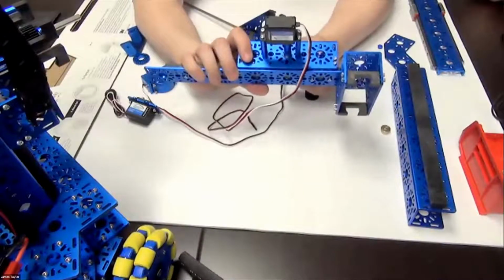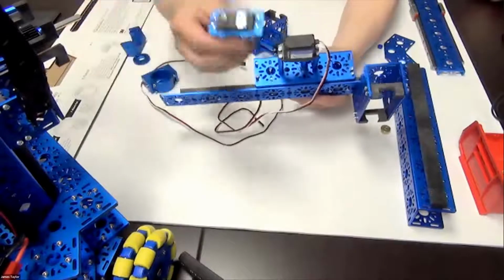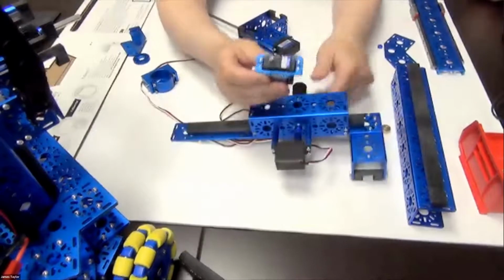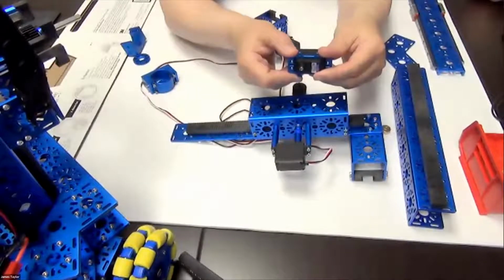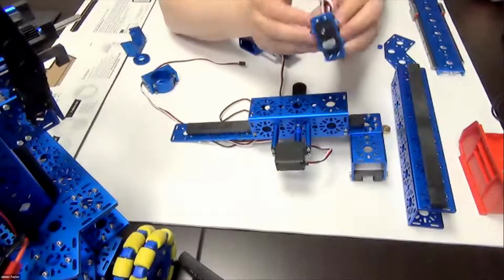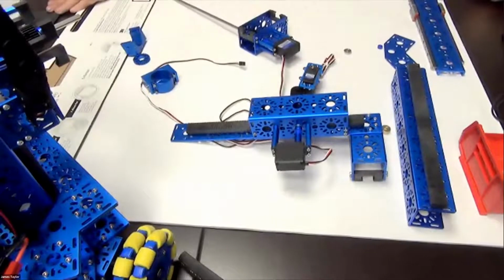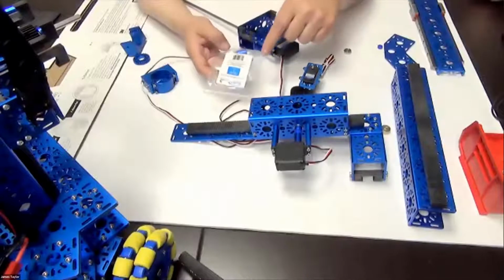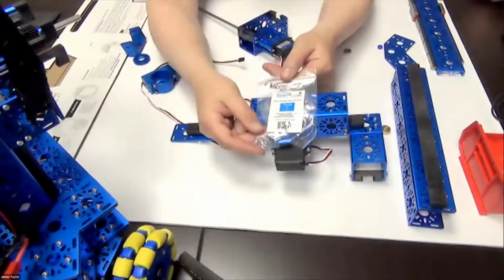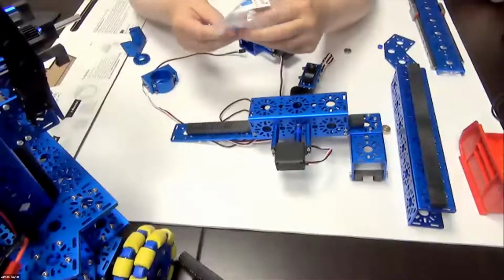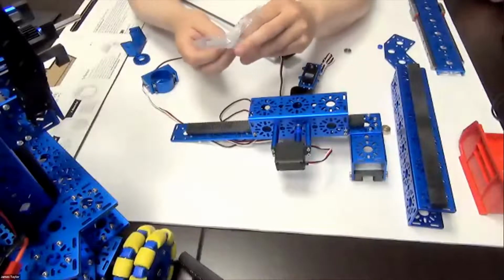So the idea behind doing this is that you would use that bracket, and put your standoffs and screw them through here, and that provides additional support to the servo motor. I just wanted to talk about that because in your assembly, you're going to see that this is one of the ways that we have put that together. All right. You will also be using the 6mm D shaft to servo hub adapter. All right, so that's a small adapter.